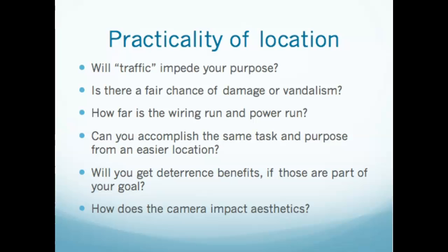But I will tell you that I'm doing a project right now in New York where there were 3 cameras on an executive floor, and the interior designer is pushing back saying, I don't want those cameras, 3 of them anyway, hanging down. I know you need them. Can you do it with some other way? And we're actually going to use a fisheye camera in a better location. And with 1 camera, I'll get the view of the 3. And so the aesthetics told me to use a different camera at a different location. So you always have to think about that, because if you put up a camera and it really looks bad where it is, you're not going to be popular, and it makes you look like you didn't think it through.